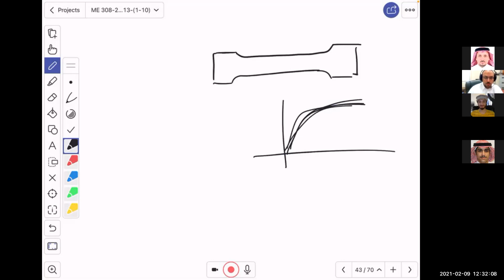Now, when you do the stress strain curve, you take the force over here and you divide it by the area over here. And that's how you calculate a stress. Is that right? Right. Now, what you want to secure is that, interestingly, we taught you that whenever you change the profile, you introduce stress concentration over here. So how come the sample doesn't fail over there?